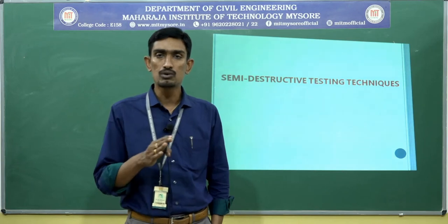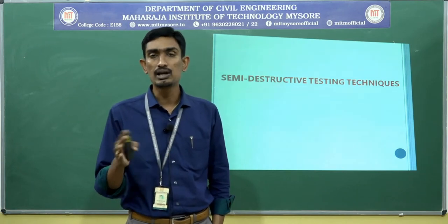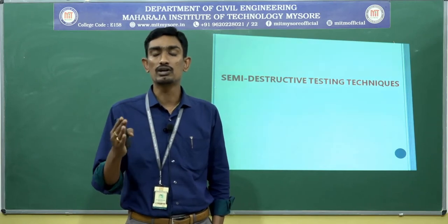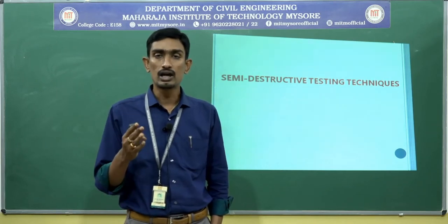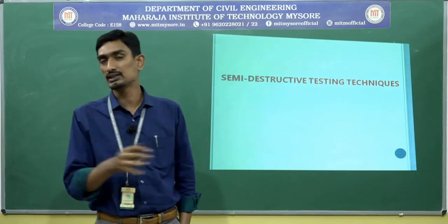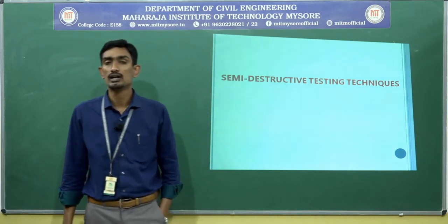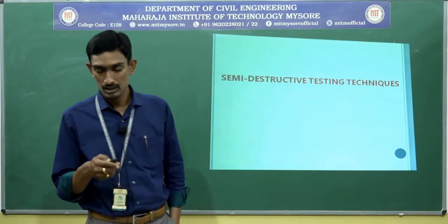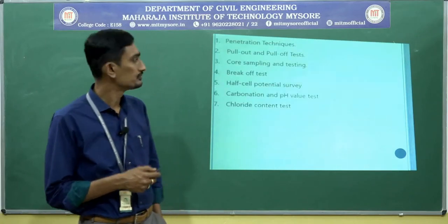That means I am going to disturb the neighboring concrete, the concrete where the test is performed, and with that disturbance I assess the strength and quality of the concrete. That is called the semi-destructive testing system. Let us go through them one by one.